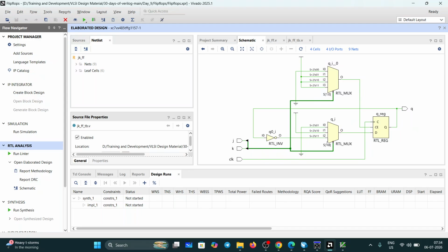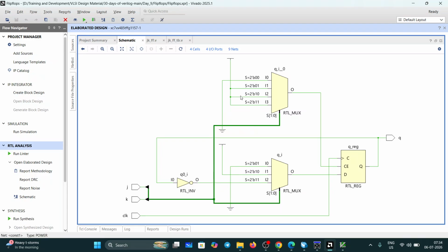So like this you are getting in terms of mux and D flip-flop, it is converting depending on the possibility. We gave the case statement, no? So it is converting like 4 cross 1 mux, and it is giving to the D flip-flop. So like this the tool is converting our code into RTL design, in gate level netlist.